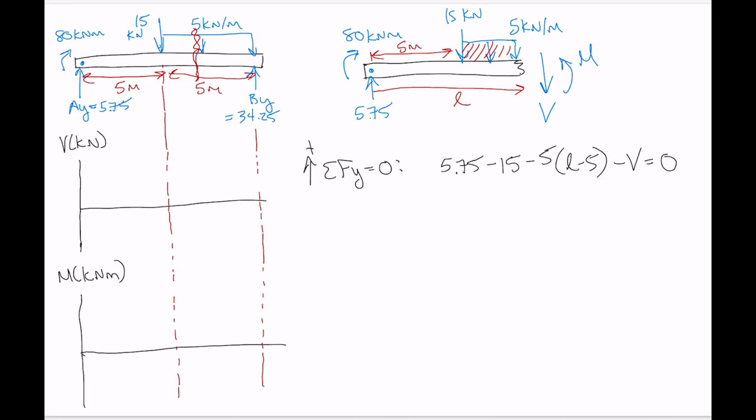Now remember that this internal shear force's sign convention is different between what's defined as a positive internal shear force and what I've taken as the positive direction for my equations of statics. The two are not related. So that's a negative shear force according to my sign convention, but it's actually a positive shear force according to the shear diagram.